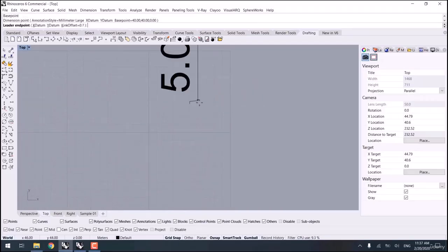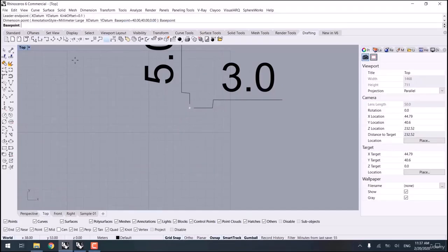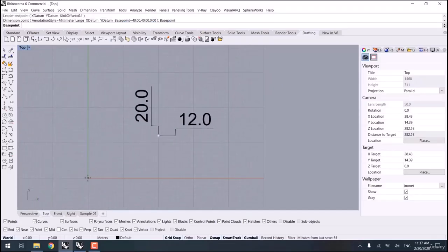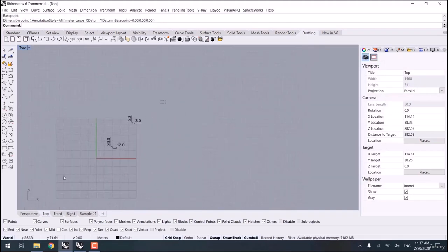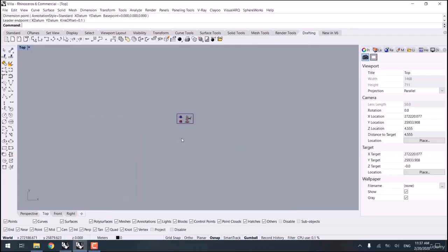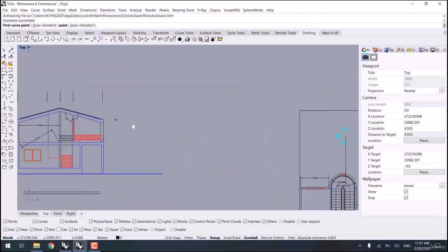Then we will have the coordinates relative to the specified base point. Check it out. This time x 3 and 5 for y, since we have modified the base point. Again, I set the base point to the origin point. Following that, enter. I delete these. Well done. Ctrl Alt L to show the hidden objects.